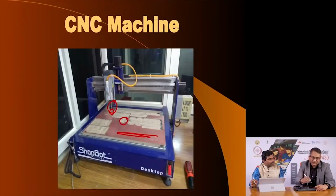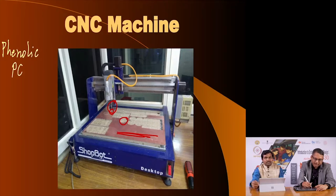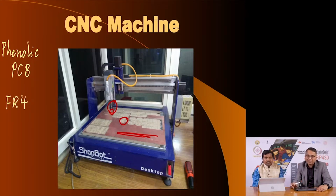You get very cheap PCBs, you may have seen brown colored PCBs. They are made out of a material called phenolic material, phenolic PCB, and we do not recommend using such a type of PCB. The good quality sturdy PCB is called FR4, and this is made out of fiberglass. This is the substrate, a non-conductive surface on which a thin layer of copper has been pasted, and this is an example of a FR4 type of raw PCB.